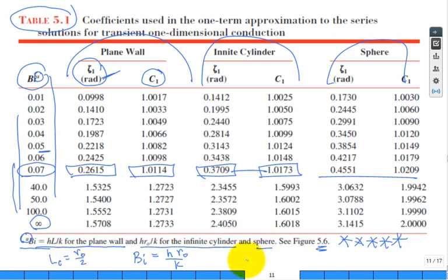And so the Biot number in this table for a sphere is h r_0 divided by k. But when I checked to see if the lumped capacitance was valid, I evaluated a Biot number and I used h r_0 over 3 k. So you can easily be off by a factor of 3 in a spherical problem, or a factor of 2 in a cylindrical problem. Guess what? The slab, the plane wall is good. This L is the half thickness in both of them.